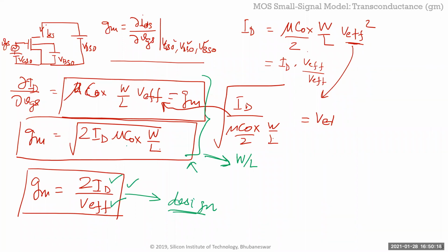Like I said, that's why I kind of forgot the other equation, because frankly, I don't know when I last used it. But all the textbooks give you those equations, while this is the one we'll be using. When we start designing current mirrors and amplifiers, I'll show you how to use this equation to actually design. It's a very powerful methodology, which honestly a lot of designers still don't use. They go to the tools and start playing around with a lot of W over L's and doing it in reverse.